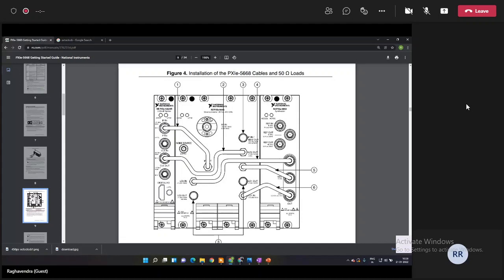You can set the IF frequency in this to say 1 gigahertz. And obviously your USRP is capable of taking that 1 gigahertz. So you down convert it to that intermediate frequency, and then you give it to your USRP, which will do all of the necessary calculations.